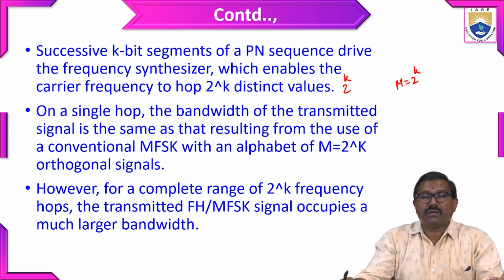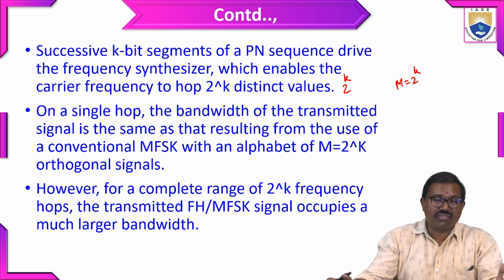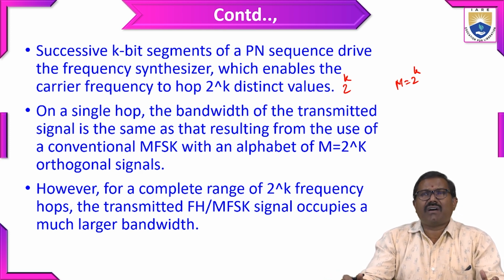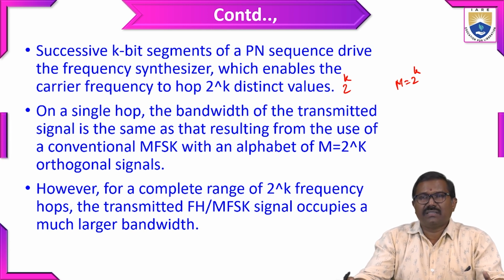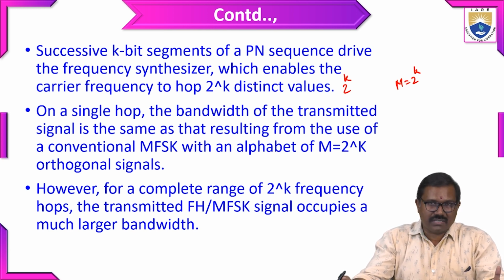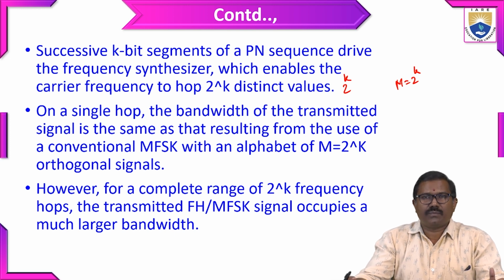By up conversion of the frequency using a mixer, or you can say double modulation. The already modulated signal is modulated again, so the frequency range increases. That is a larger bandwidth. Whenever a larger bandwidth is used, it becomes more difficult for a person trying to catch the signal. So that is why.